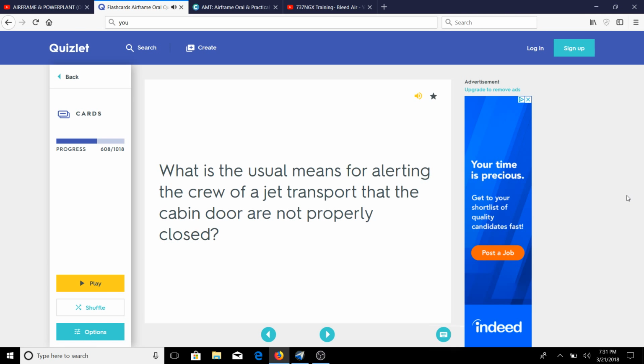What are the two items that should be considered during inspection of a magnetic compass? 1. The fluid must be clear. 2. The housing must be full with no bubbles. 3. The card must be legible and the lubber line intact. 4. The compass should be properly calibrated. In what way do magnetic fields generated by electrical equipment and steel parts in the airplane affect a magnetic compass? Stray magnetic fields deflect the compass from correct alignment with the Earth's magnetic field.